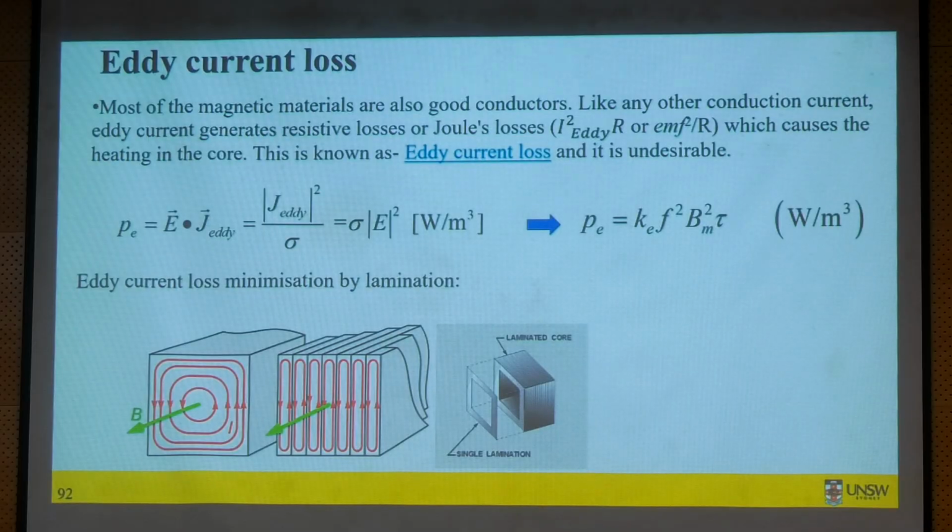And we know how to reduce eddy current loss in the steel. We use laminations and stack of lamination. The same concept in fact can be also used for magnet. Okay, especially like concentrated type winding which has been proposed for PM machines, the flux produced by the current have harmonics.